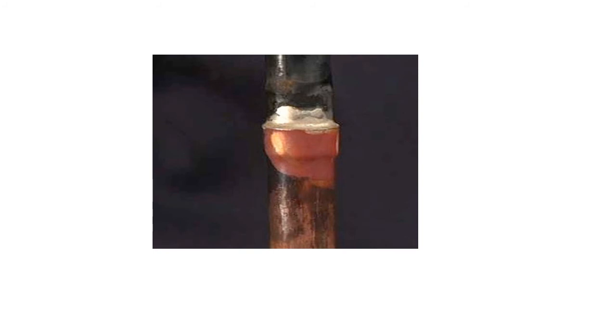One note on brazing for the ACR industry. Whenever we braze in piping that is used in refrigeration or air conditioning, we must use a nitrogen sweep to prevent scaling on the inside of the pipe. Nitrogen is an inert gas, so it keeps oxygen out of the pipe so that scale will not form. Scale in the pipes of the refrigeration or air conditioning system will be very detrimental to the operation and longevity of that system.